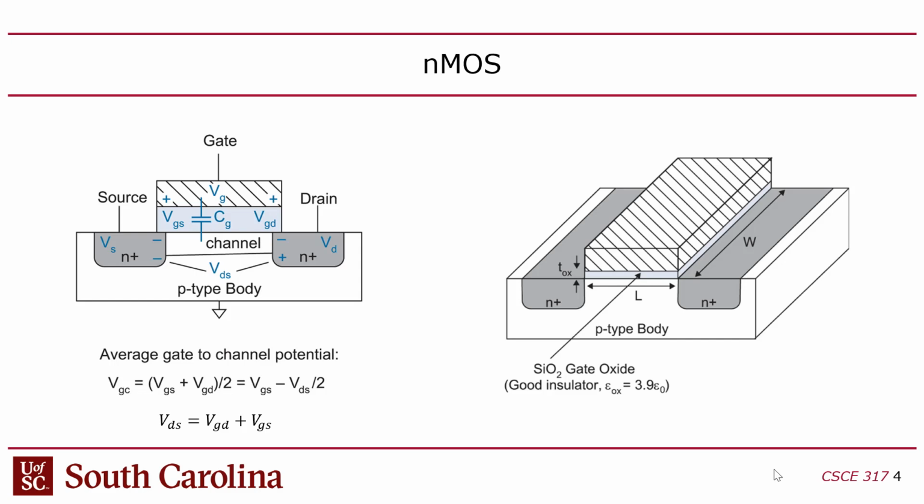However, on the other hand, there's a width, which is the other dimension. The gate and the channel are the same size, because it's like the top and bottom of a sandwich. So you have a width and a length. The width shrinks at the same rate that the length does. Moore's law said that we double the number of transistors every 18 months or 2 years. That's how it used to work. What that's referring to is actually the product of length and width, the area.